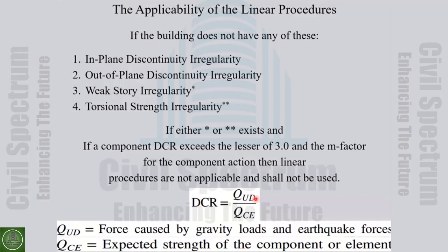So the first concept that we had for existing buildings, and we talked about that a little yesterday, is that we divide all the responses into deformation control or force control response parameters, ductile ones or brittle ones.